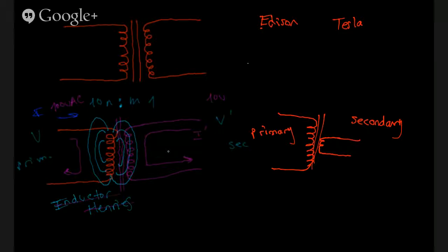Nothing is a perfect conductor. It'll have an inherent resistance, and we know how to find that resistance. And because resistance is never quite zero, according to Ohm's law, the voltage that we put in on this side, we're going to get a lesser voltage over here because of voltage drop.